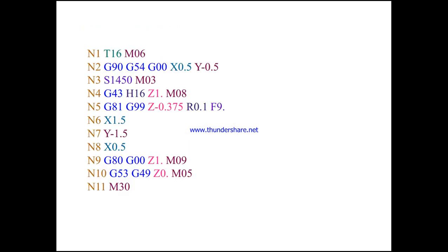N1, sequence of operation: N1 T16 M06, where M06 is the tool change, so the tool has to be changed to tool number 16. So the tool has to change here. That is what we are having.